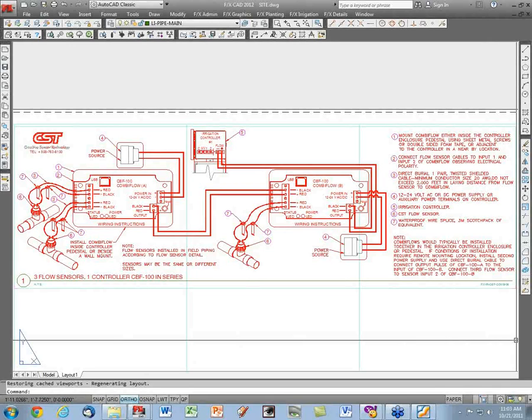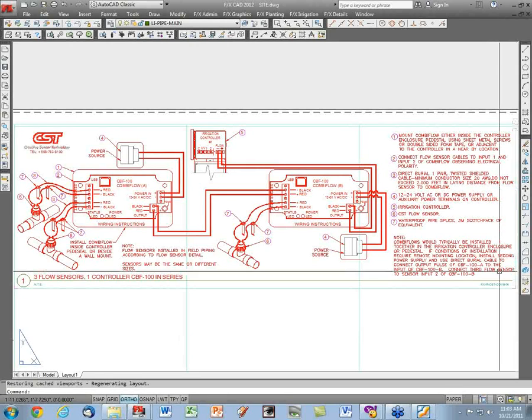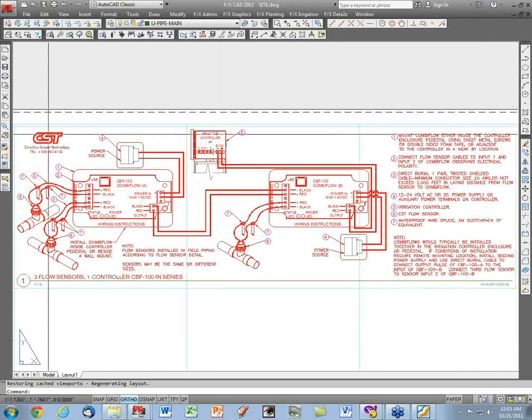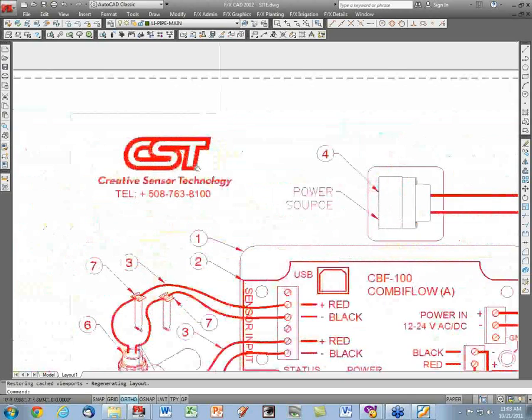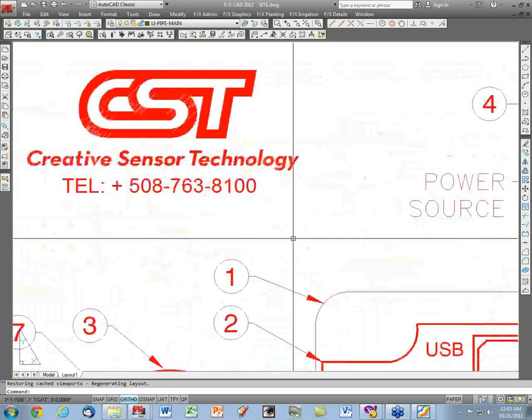That's the kind of thing where I say, call our customer service line and we'll help you with it. We have had some where we've totalized separately and then come out of two separate totalizers and combined the flow to go into the flow input of a controller, in terms of alarm and shutdown features. And we put the telephone number on every one of these details for that very reason.